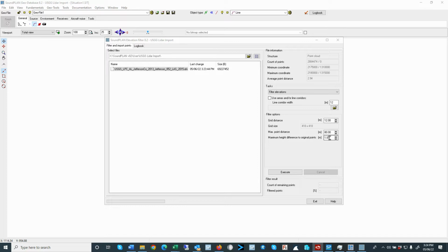I just want to point out that the program thinks this feet data is in meters, so it's actually feet. So these inputs actually mean we can increase the maximum distance to 200, and then here maybe to 2 meters, which actually means it's still within 0.6 meters. Let's make it 1.5, and then 200. So it's much more detailed than we think it is.